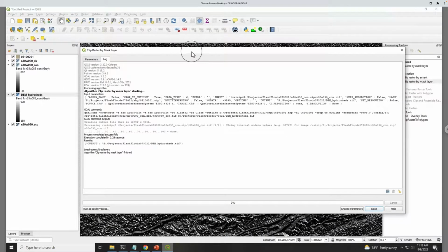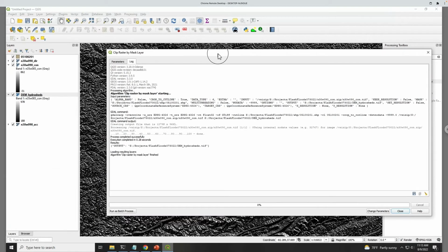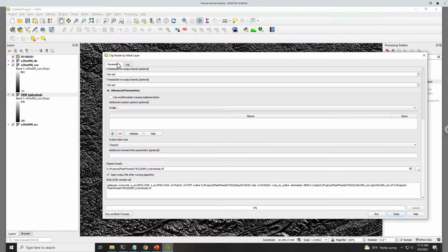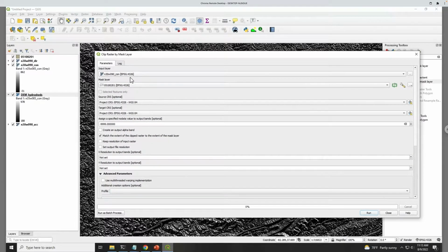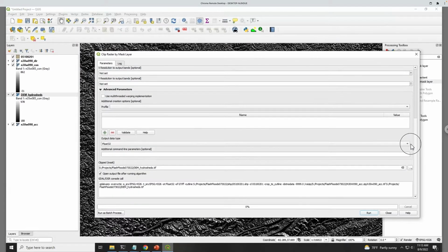So that's all for the DEM data that I processed. I'm going to repeat this process for the other three. For flow accumulation, the same setup, but you need to change the file name to, here I used FAC.